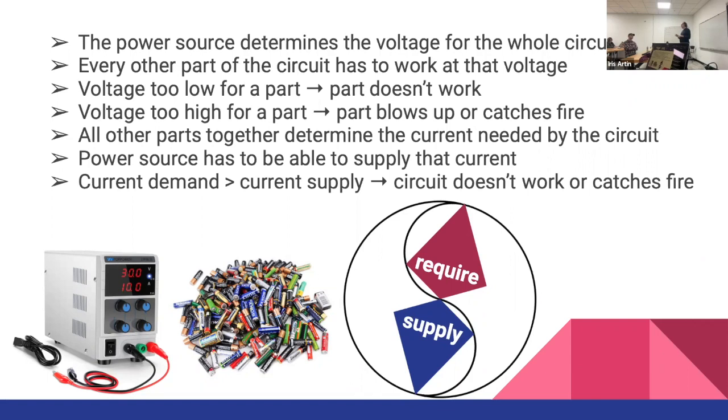And then, if you ask it for a little more than it can give, but not too much, you can get into the my-circuit-is-being-kind-of-flaky problems again. And so the other thing that is worth checking if your circuit is being flaky is whether your power supply is able to supply as much power as you ask it to give. And again, it's a good idea to follow a tutorial to save yourself from this kind of problem when you're a beginner.